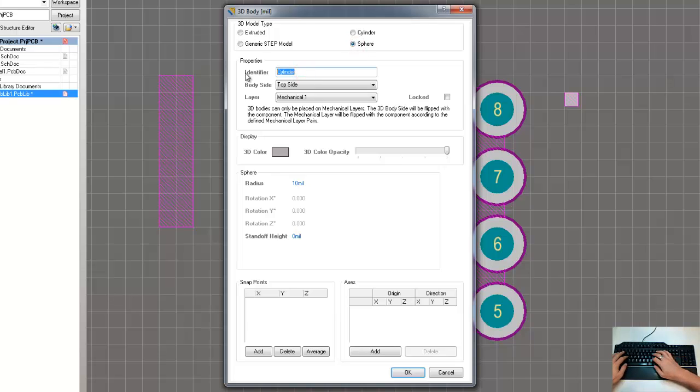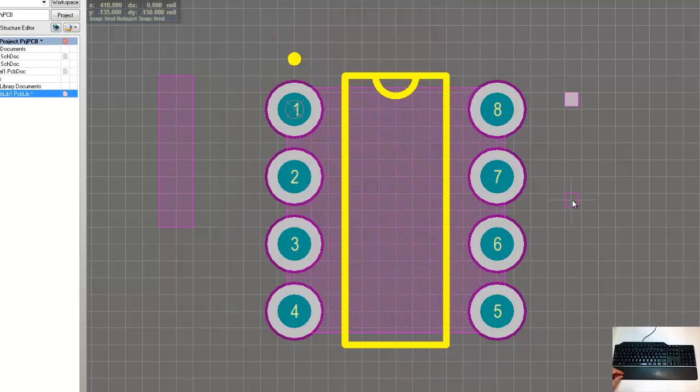If using the basic shape tools, make sure to give each different shape a descriptive name for the purposes of simplifying editing. The simple shapes can be difficult to line up accurately, but can be useful if the Altium coordinate system is used accurately.